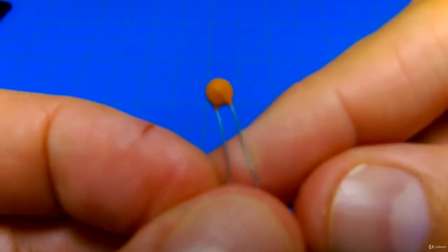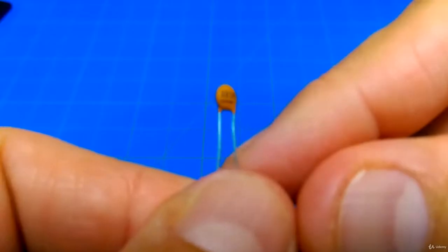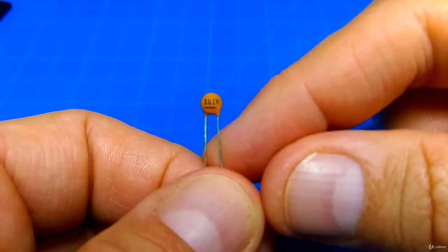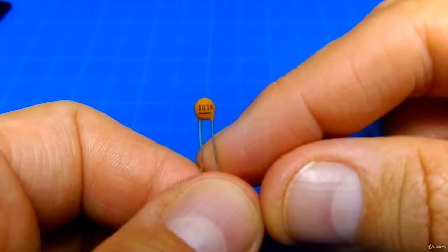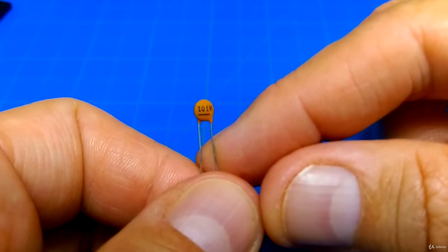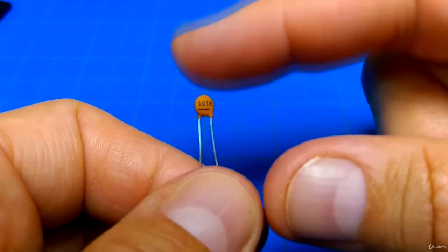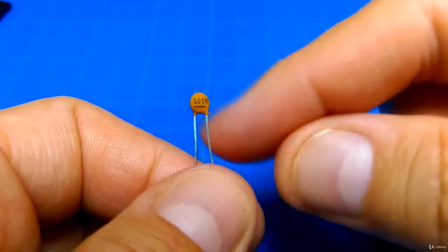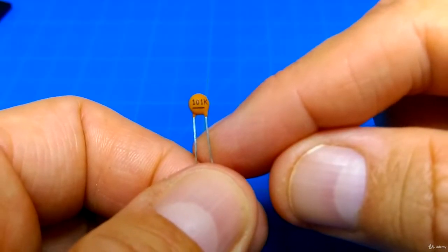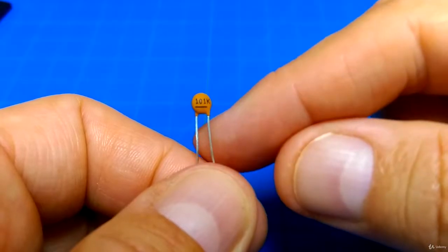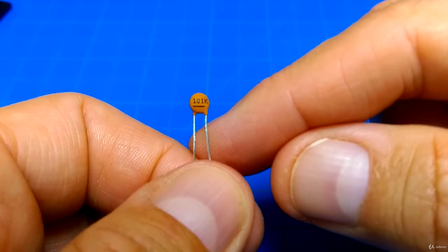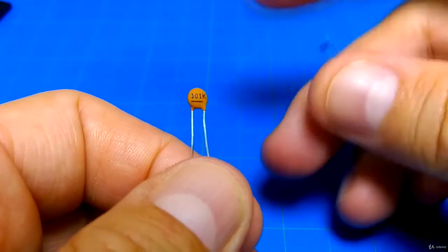Let's take a look. Okay, so this is a ceramic capacitor, and you can see it says 101. All right, so this is the value of it, and I'll show you how to read these later. But this is usually measured in picofarads, and so it's 1, 0, and then the last digit is a multiplier. But again, sometimes these things have different kinds of encoding, so you gotta make sure you're reading it right, and different vendors do different things, and you can always get your meter out and check it.